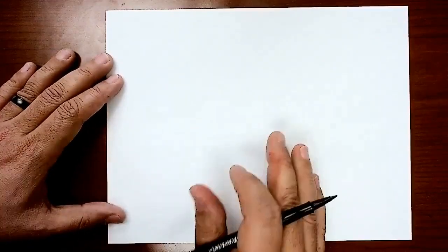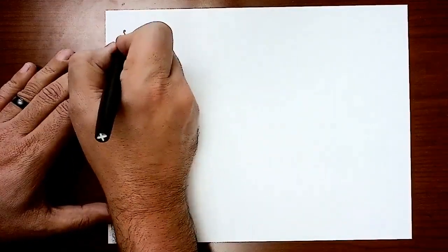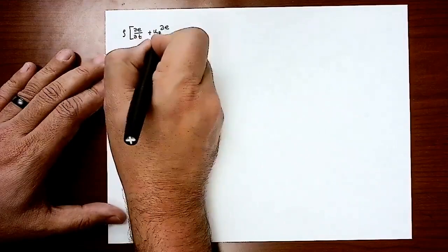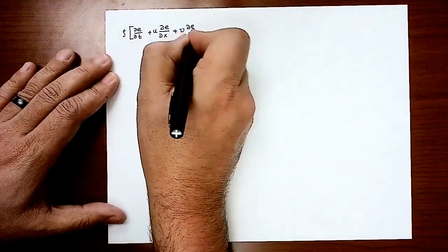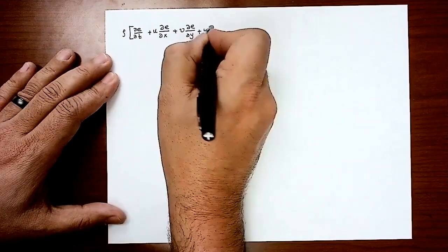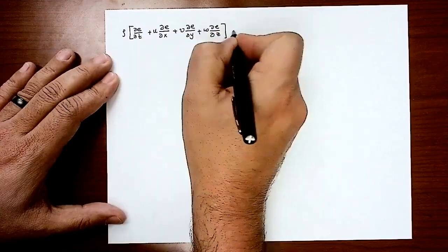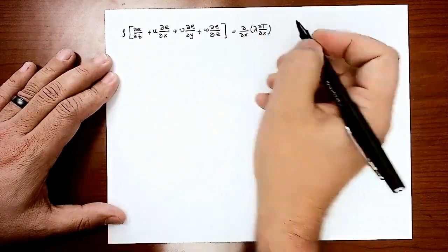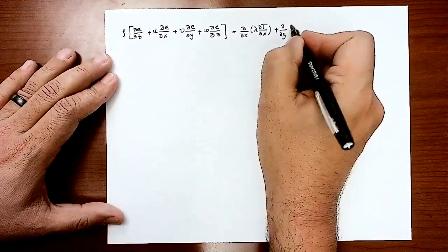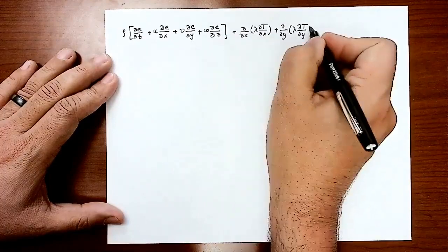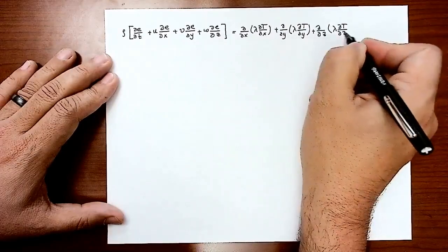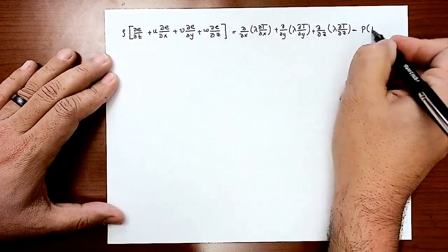You're going to end up having the following equation, which is the closest form to the energy equation: rho partial E by partial T plus U partial E by partial X plus V partial E by partial Y plus W partial E by partial Z equal to partial by partial X lambda partial T by partial X plus partial by partial Y lambda partial T by partial Y plus partial by partial Z lambda partial T by partial Z, minus P times nabla dot V,